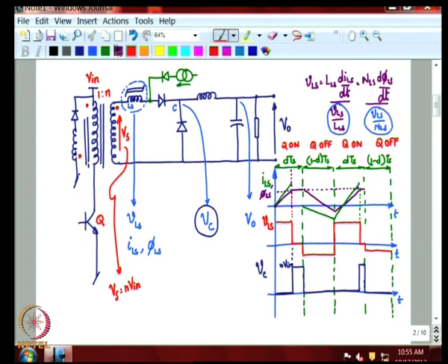So, by controlling the rate of current that is going to flow in the saturable inductor in the reverse direction, you can control the amount of negative voltage that appears across that inductor, and as a result control the flux rate within the core.